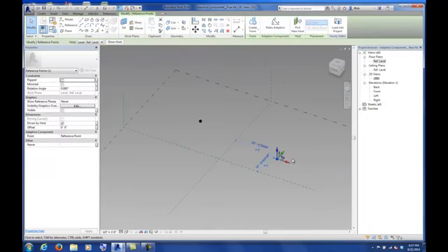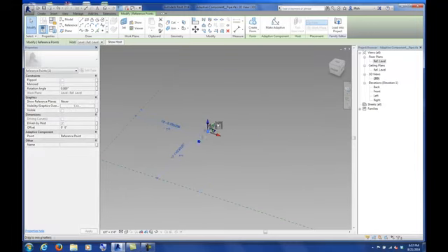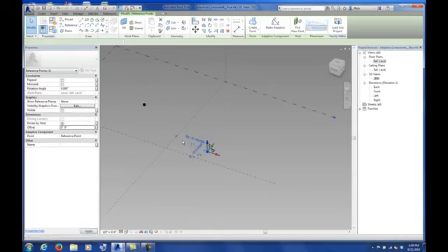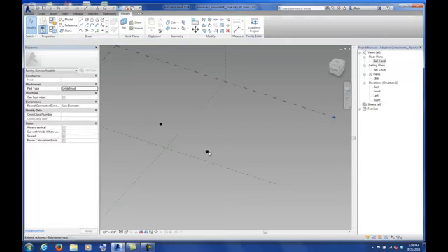When you select the point, you get these coordinate crosshairs, kind of probably if you're used to working in 3D Studio Max or Maya, you'll see these a lot. But basically you can drag, if you pick the blue, that drags it in the Z, the green is in the Y, and the red is in the X. So if you want to move your components around, you can do that. I'm going to just kind of move them a little bit closer together. And again, it doesn't matter where they exist on your screen. They can be anywhere.